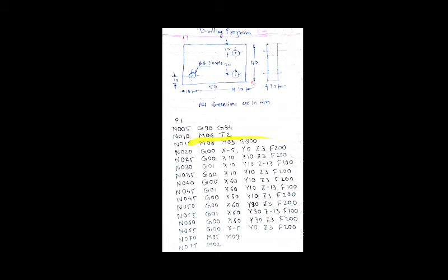First we moved to the safe position, then we moved the tool above the first hole position. In the next block we drilled the first hole with X coordinate 10, Y coordinate 10. In the next block we removed the tool from the workpiece, at X10 Y10.